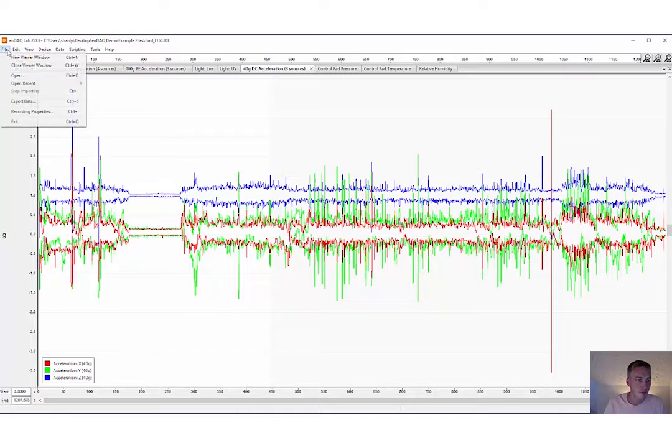How many samples? I'm sampling for 2 hours at several thousand hertz, so it's a lot of samples. And you see this envelope view where it looks a little funny, and we get questions from that sometimes, like, why do I see these two lines? There should be just one line for my x-axis, y-axis, and z-axis.